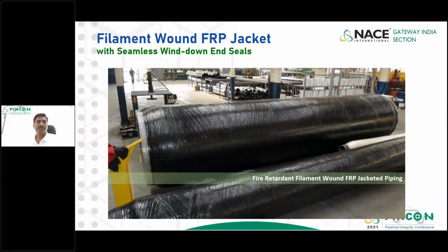The filament wound FRP jacket having wound-down end seal, which is bonded and monolithic to limit the leak spread and prevent corrosion. This system can be used above ground, below ground, within the fire zone area, and outside the fire zone area.